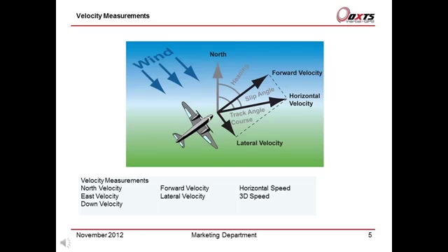The RT measures true heading, so it is possible to separate forward velocity from lateral velocity to give horizontal velocity. In the example here, the aircraft is flying straight into a crosswind. The track or course over ground the aircraft takes is not the same as heading because of the crosswind. This is the same effect as slip angle in cars.